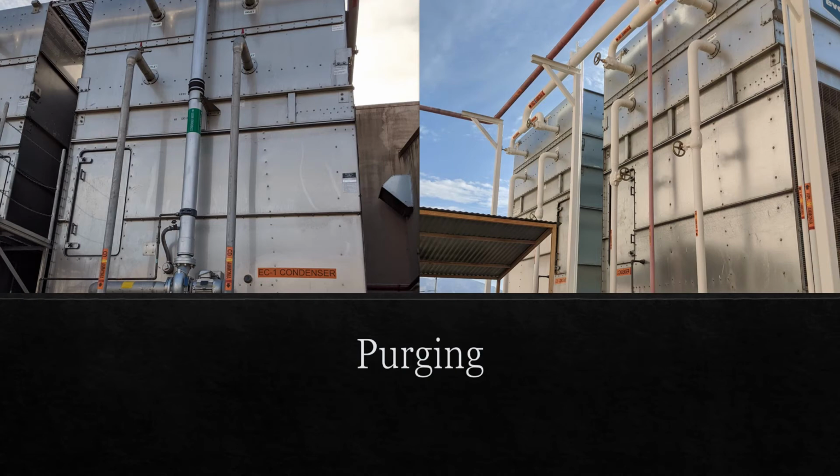Section 7.2.4 requires that systems be configured with a means to remove air and other non-condensable gases from the refrigeration system. Typically, condensers are configured with purge valves on the condenser drain piping to facilitate purging of non-condensable gases, as shown in the picture on the left. Occasionally, however, you'll run across a system lacking these valves, as depicted in the image on the right.